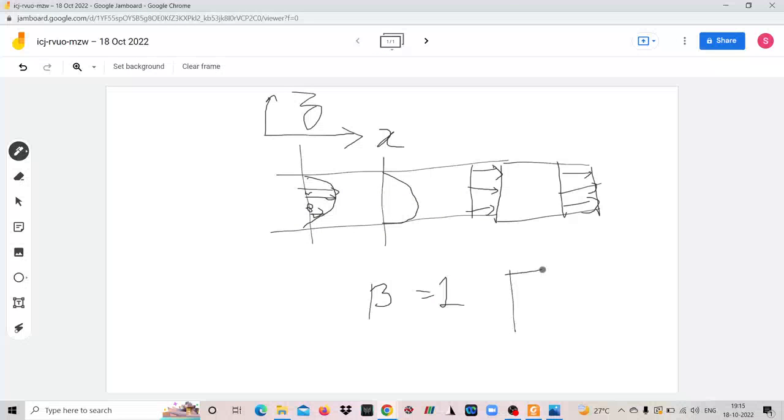Okay, you can derive it, no problem. Say there is a velocity distribution something like this. It means a perfectly rectangular variation. Everywhere say the velocity is u. So for this case you simply derive the value of beta and you will find it is 1. But in the parabolic case it will not be equal to 1. Yeah, for this case it will be 1.